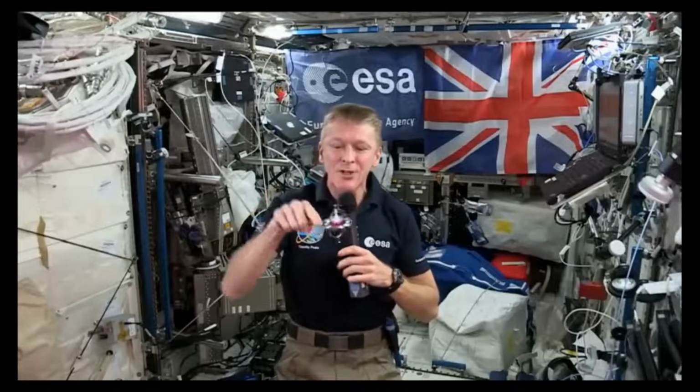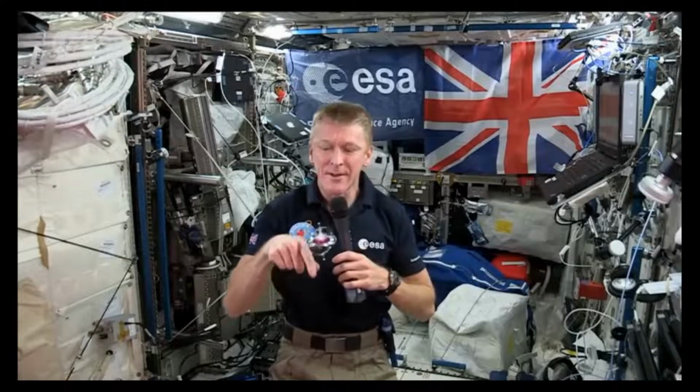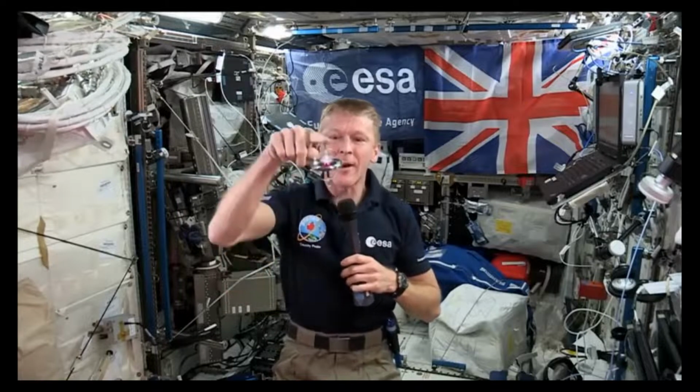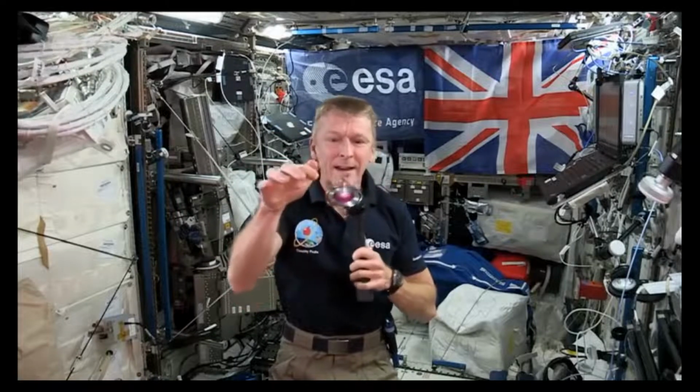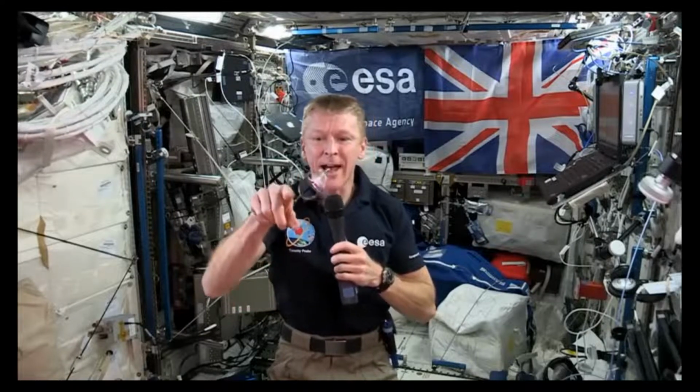There is one more important result of the interaction between a spinning spacecraft and an applied torque. We all know that spinning footballs and spinning rifle bullets travel faster and farther than non-spinning ones. This is because spin makes them more stable and resistant to outside torques. The faster they spin, the more stable they become. This stability is referred to as an object's gyroscopic stiffness or rigidity.